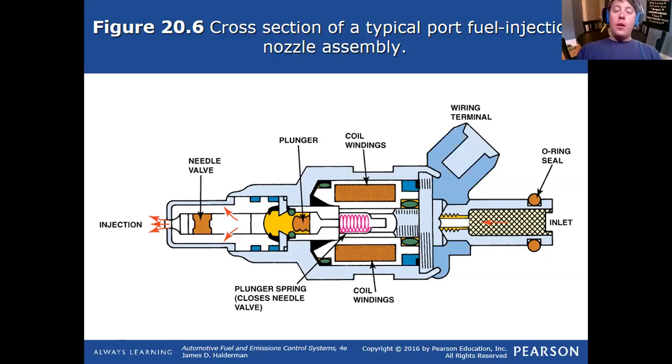It can be in the injector, it could also maybe be in a fuel pressure regulator, but every injector I've ever taken apart has always had a final filter in it. If we look right here, this little meshed area, that's where that finer final filter will be. Sometimes you'll hear them referred to as a basket. I've seen the terminology, they'll talk about the fuel injector basket. That's the final screen.